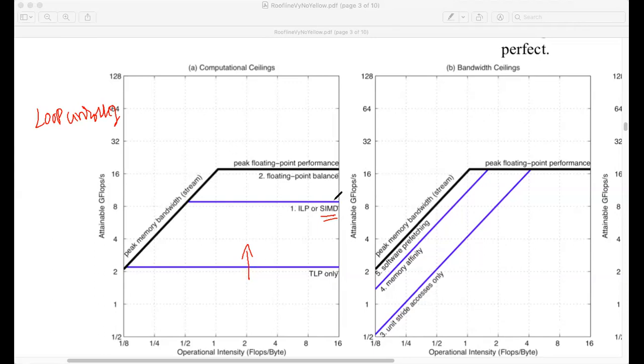It is substantial. So through loop unrolling, we are able to increase the operations per cycle. What happens is you keep on unrolling. At some point, what happens? Let's say initially compute is somewhere here, and as you keep on unrolling, at some point this line will hit here, and the memory becomes a bottleneck, rather than the FPGA logic that is present.